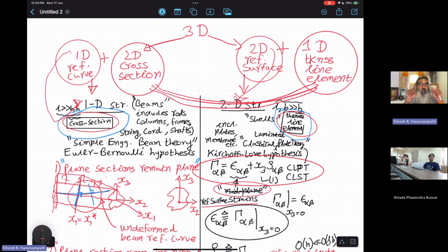It could be closed also. It could be a box beam, like we have indicated before, or it could be a circular tube, circular shaft, which is thin walled, hollow circular shaft. So then when you have something like that, you again have a smaller dimension associated with the cross section, which is the thickness divided by the diameter, or thickness divided by the dimensions of the cross section. If it is square, the length, the width, or the height. So keep this in mind, that those are interfaces between 2D and 1D, because you can model both as 3D, 2D as well as 1D, many of the aerospace structures that are available.